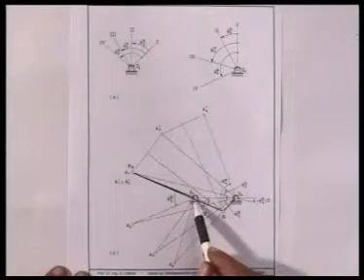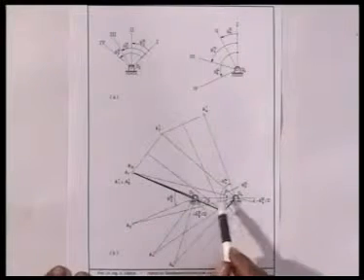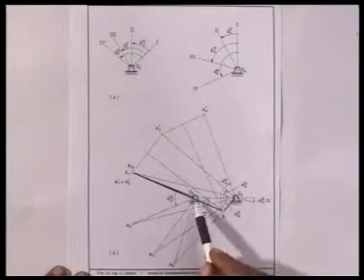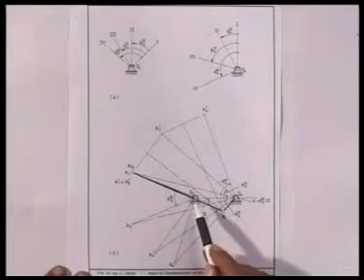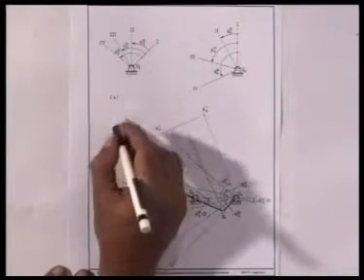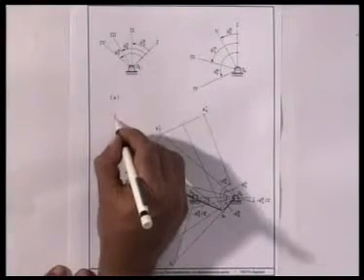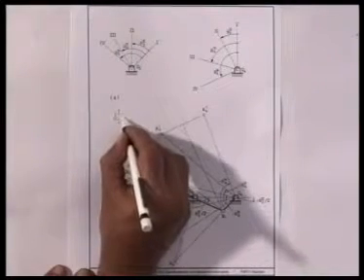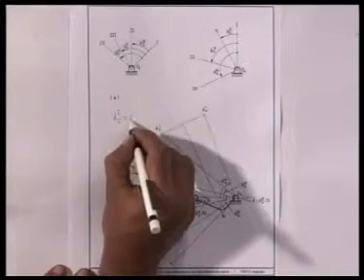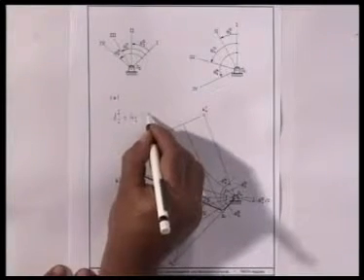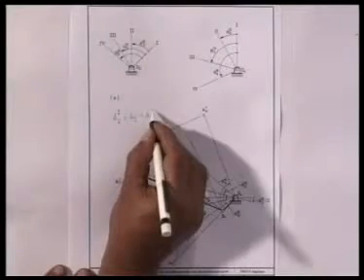As before, we choose the fixed hinge locations O2 and O4 conveniently. As we know, A1 cannot be chosen arbitrarily any longer. We choose A1 in such a way that the inverted position of A2, which we call A2 1, coincides with A1, which is same as A1 1.